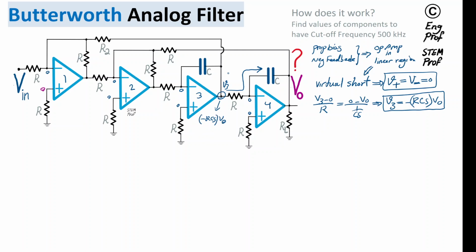Now the same thing can be done for op-amp number 3, which is in the same configuration, the inverting terminal configuration. As a result, I can multiply this whole thing by minus RCS again to get V2, the voltage at the output of op-amp 2. So here we should have minus RCS squared times Vout. Again, I multiplied this whole thing by minus RCS, same as what I did for the 4th stage.